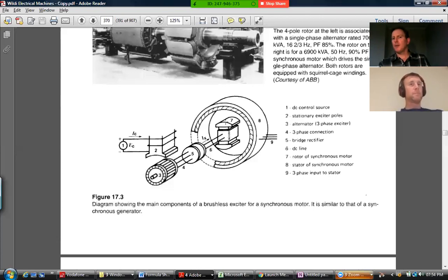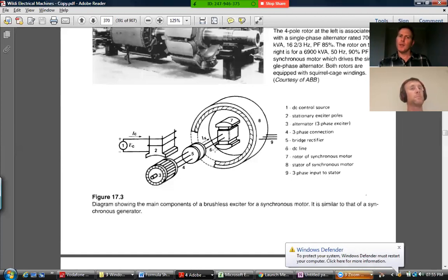How do we get it free? We've put a bar magnet in here, a big fat one. It would spin. We don't need any extra power to actually make the magnetic field. But because it's an electromagnet and the magnetic circuit is not infinitely permeable, you need some amp turns to drive that flux, to establish that flux. You need some MMF, magnetomotive force. So you have to have some current in here, and you have to end up with some I squared R power losses, or volts times amps if you prefer.